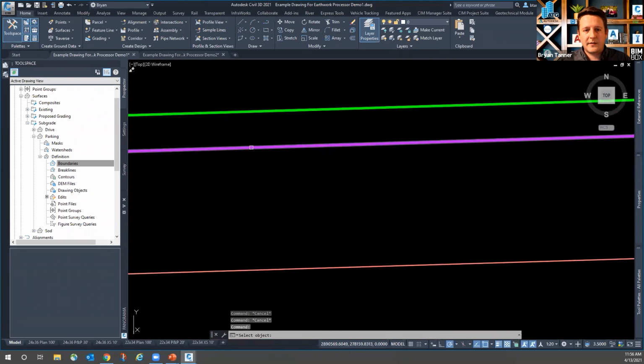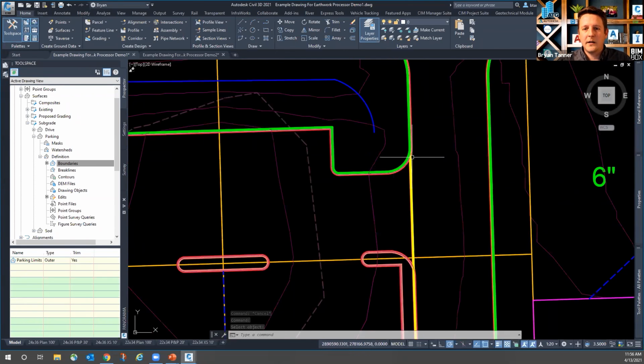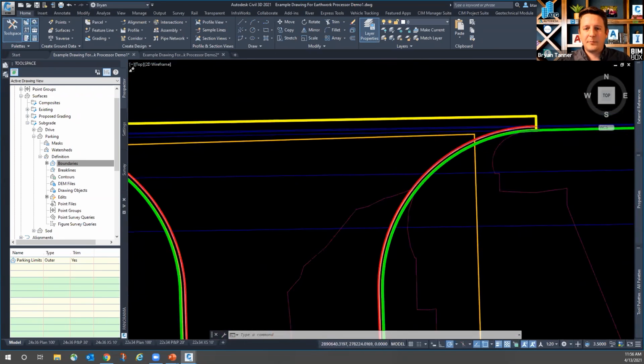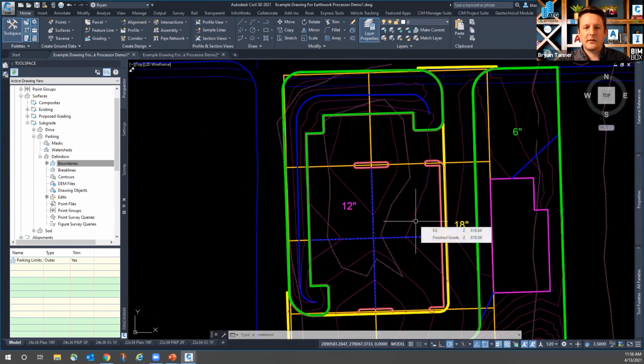You also notice that there is a slight offset between my sod limits and my subgrade limits for my parking lot. Same thing for my drive versus the sod. And that's because one of the workflow aspects that we're going to address within this is compositing these surfaces together. We're going to create 3 different subgrade surfaces, but we also need to define not just those subgrade surface limits, but composite those together into one overall machine gradable, GPS guided machine gradable surface that is uniformly defined.